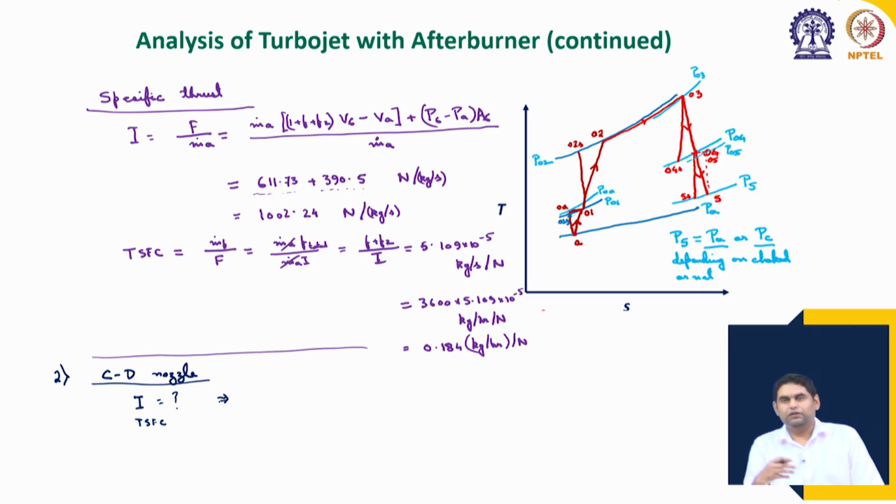So, what do we expect? I had discussed that in general, getting a momentum thrust instead of pressure thrust is more beneficial, because with momentum thrust you get more efficiency in terms of getting more thrust with the same amount of fuel. So, for this same case, we expect that the overall thrust should be a little higher, because we are now converting the entire thrust to momentum thrust.